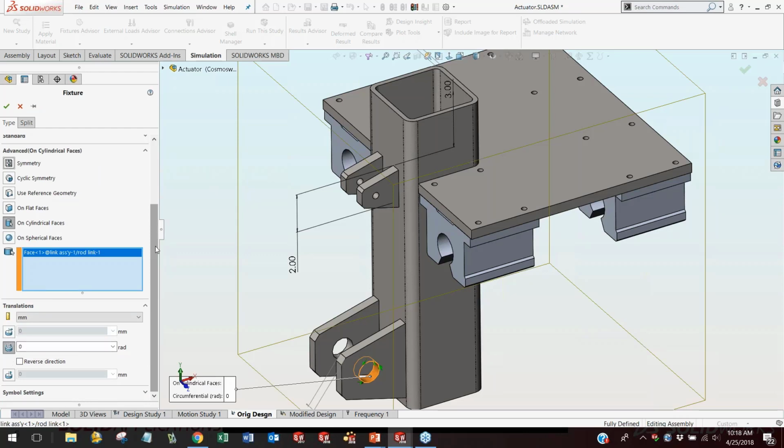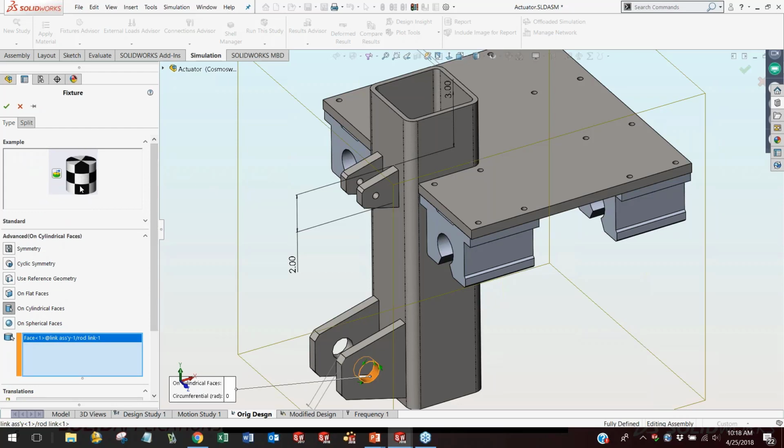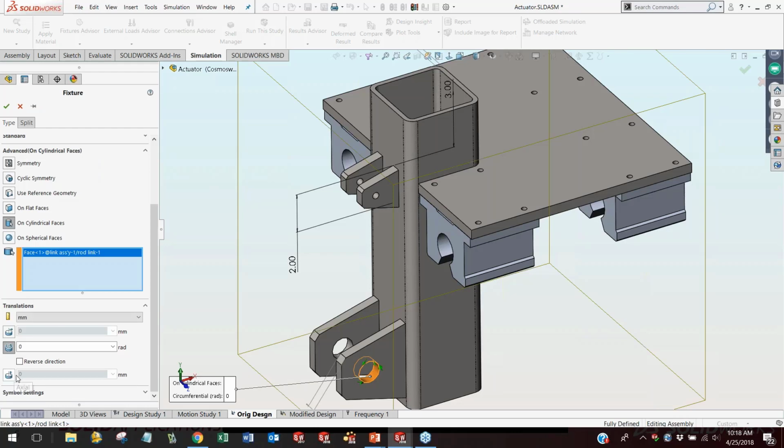We have three different types of motion that we can prevent something from engaging in, and you get an actual little picture here that gives you a cartoon of what it means: circumferential restraint, axial restraint, and radial restraint. That just gives you an idea. These little tooltips help your brain to quickly pick out what these different types of restraints are. One of the other things you can do is activate something and put a non-zero value in there, in which you're telling it you are going to rotate, or move along the axis, or expand a certain amount. So it's got quite a lot of control.